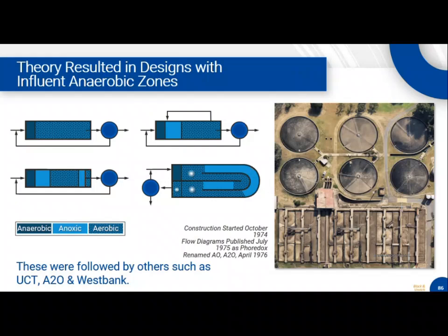Unless we're independently wealthy and our collection system gives us 110 milligrams per liter of VFAs, then we can be a little sloppy. But as you bring that down, you just have to have these more complex reactor configurations to dial in that carbon addition for PAOs, right? And make sure you have ideal conditions for them to grow in.